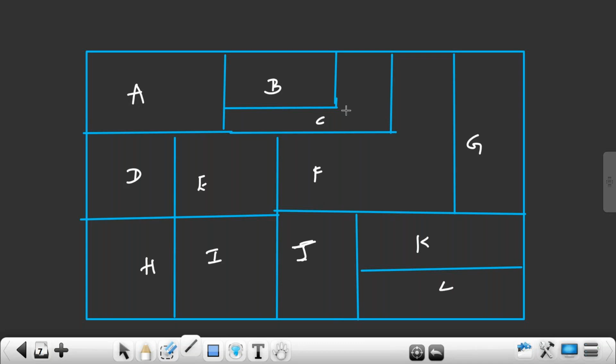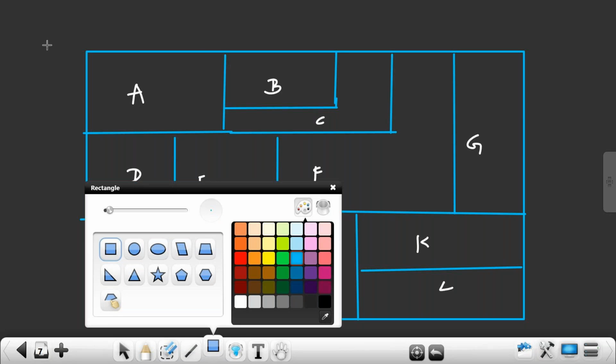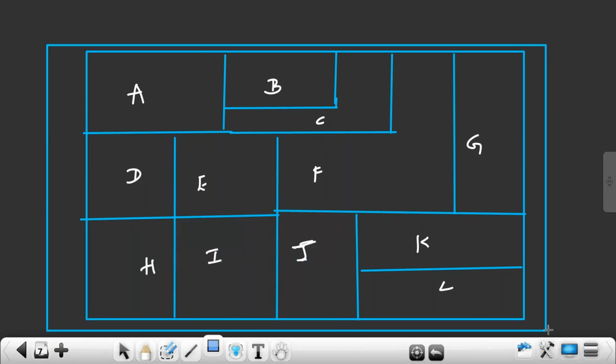So we engineers, when we go to industry, right, we work on what level physical design? Block level physical design. The person who is fitting this entire chip into different blocks, those are called as top level designers. This is what? Top level designer. Or they are called as chip top designers. So chip top, they will work at full chip level. They are responsible for dividing into what? Blocks and integrating all the blocks.